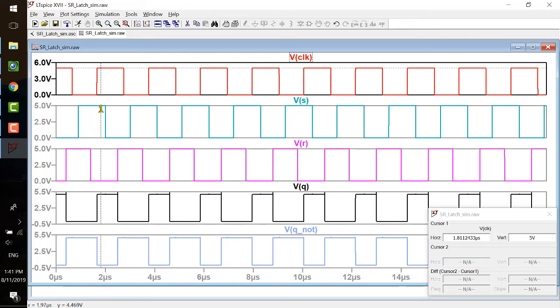And now let's take a look at what the status is here. It's 1, 0, which means it's trying to set the result. So the result is getting set, right? Which is making sense. And then you finally have 0, 0 afterwards, which means it is going to memorize the 1 here. It's going to be memorized until here, and it is, okay?